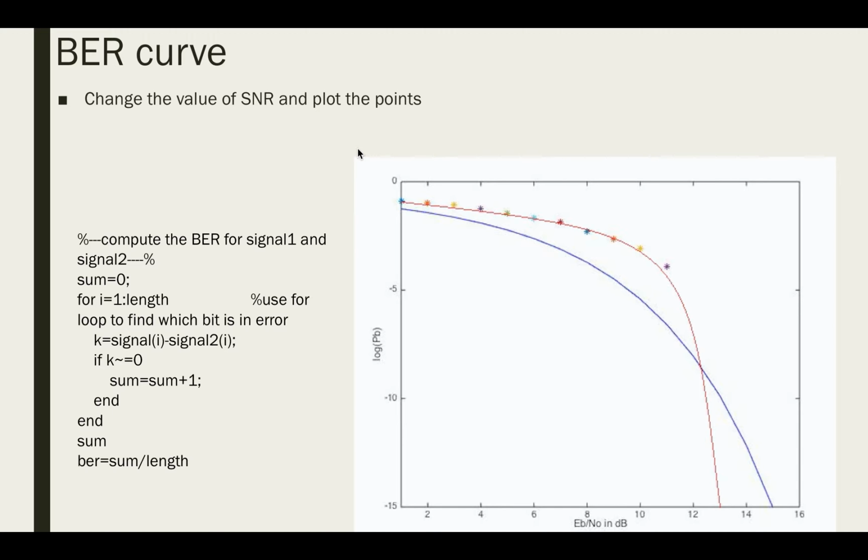We can see from this result that before the SNR increases to 13, the pure QPSK system has relatively low BER and performs well. However, after the threshold value of 13, the QPSK with OFDM system beats the QPSK system with lower BER.